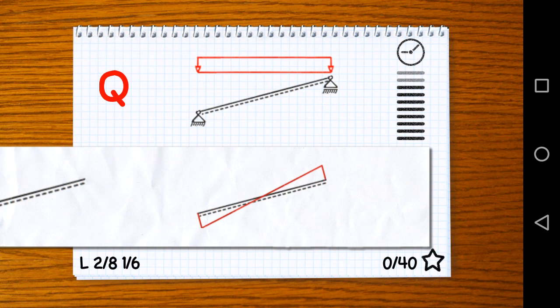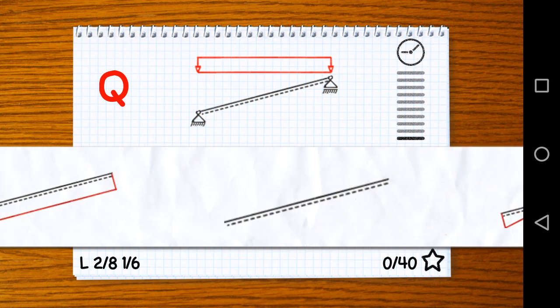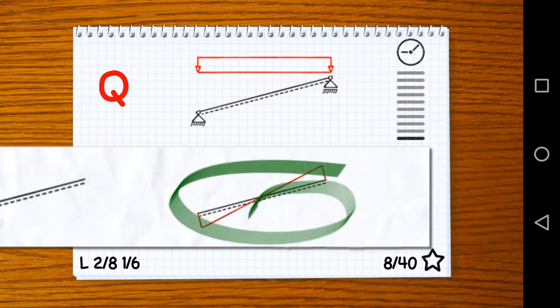Even a single force can create a moment in the bending distribution, but there we didn't have a force to make a jump or something. So shear forces, again, we look at the beam from the right to the left. That's our trick, right? On the right we have a roller support, on the left we have a pin support. The loading is a constant distributed load. Okay, that means our shear force is going to be linear. It's going to go from the right to the left, downwards linearly. So it can only be this one here.